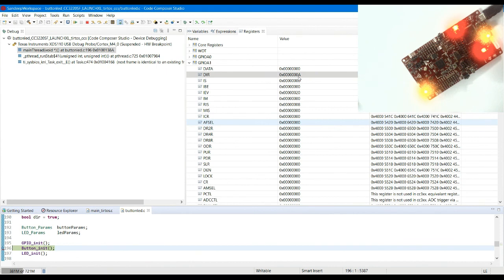I'm sure it's not very clear to you. I will try to clear it up in a separate video session, because this is a bit more complex into the ARM architecture. So right now just try to understand that 2 pins have been activated as output pins, because A is 1010, and those are basically the pins that have been considered in the direction register.